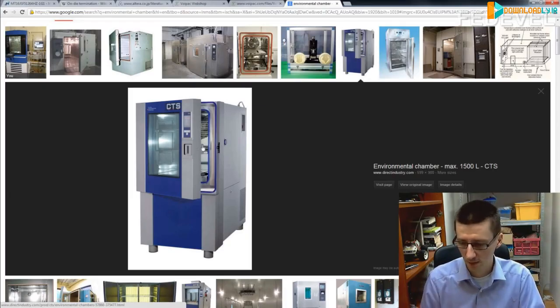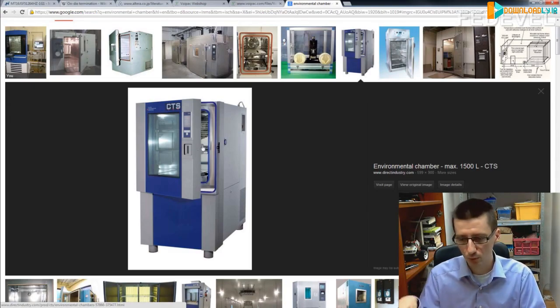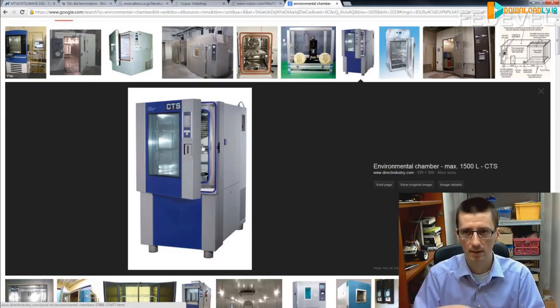How to do it? Prepare a simple functional test. So you are just testing in a loop all the peripherals which are on your board. For example, for serial port, just send something out, use a loopback and receive it and check if it's the same.